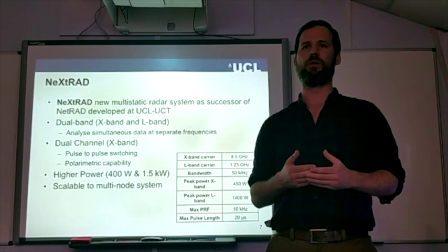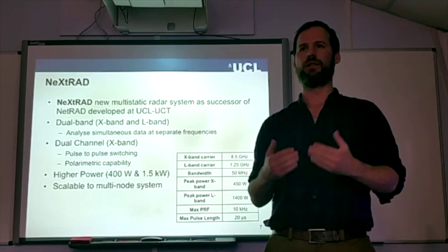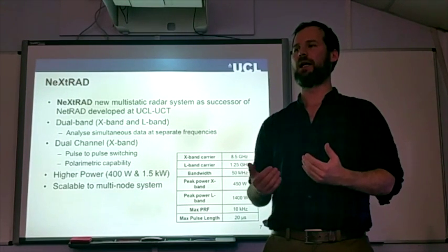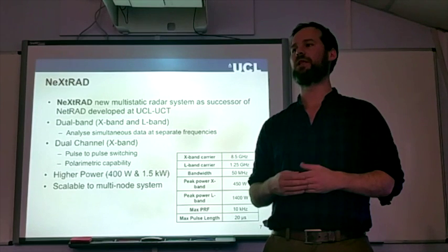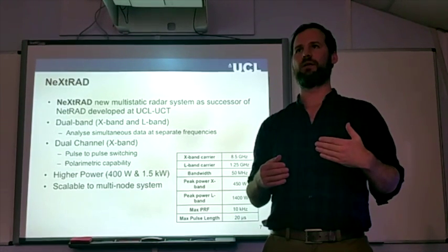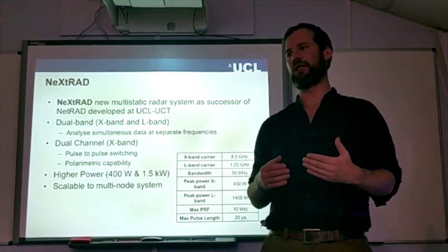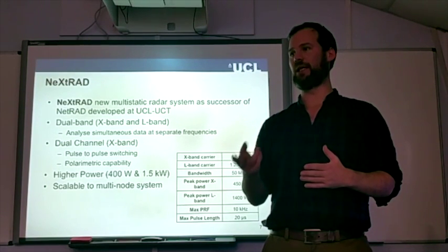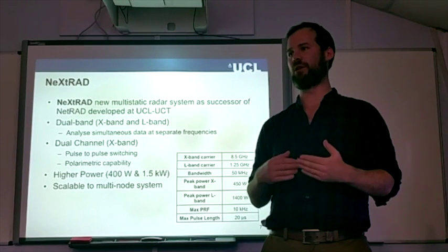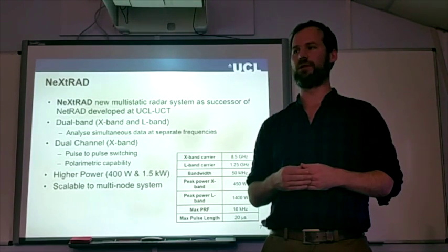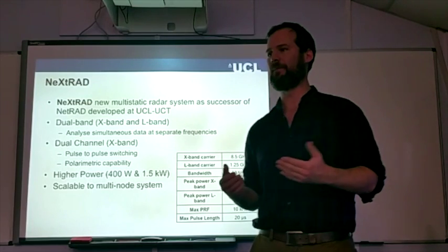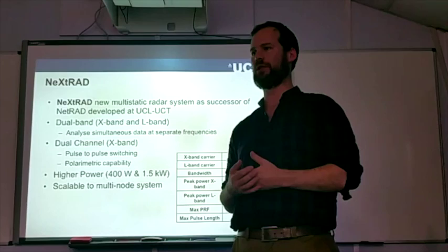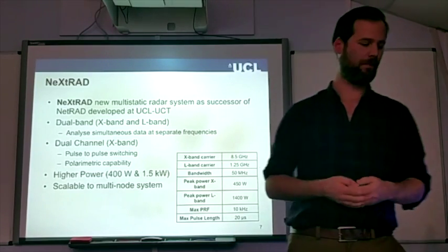Yeah. And so we will be looking to, in the initial stages, transmit a single polarization and measure that and cross. Okay, so you can do either vertical or horizontal. And then in the future, we'd look to obtain a high-power solid-state switch, which would allow us to go HV, pulse to pulse on the transmit side of things. So that would give us full. Yeah. But we're gonna walk before we run, and we're limited by the single HPA. Yeah. But that's the goal of Clayton, absolutely.